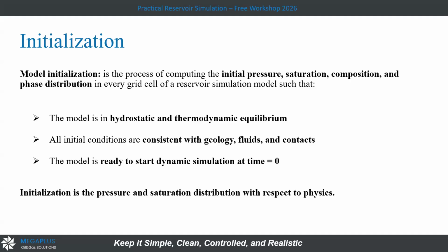Model initialization is a process of computing initial pressure, saturation, compositions, and phase distribution in every grid cell of the reservoir simulation model, such that the hydrostatic and thermodynamic equilibrium, which is the initialization by equilibrium, holds. All initial conditions are consistent with geology, fluids, and contacts. As I mentioned, we have to respect the property and structure maps and features, of course. The model is ready to start the dynamic simulation at time zero, the initial condition.